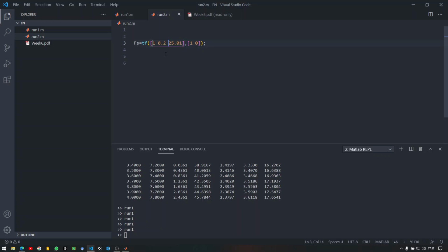So by adding dynamic parts, or the poles and zeros of the controller, to the system, I'm updating the loop transfer function in a way that is desired in terms of the root locus plot.